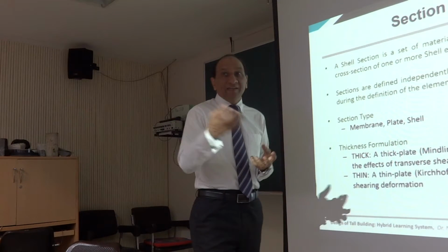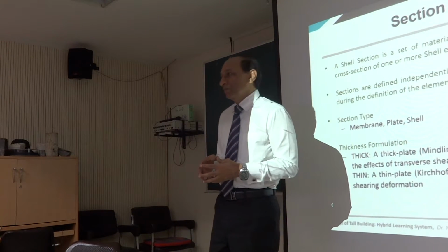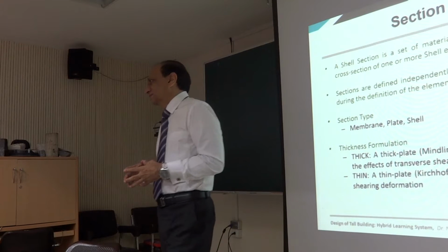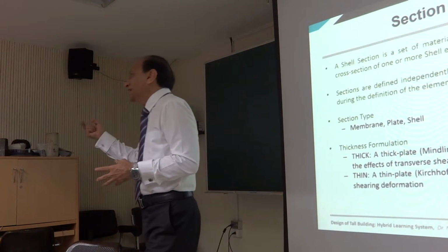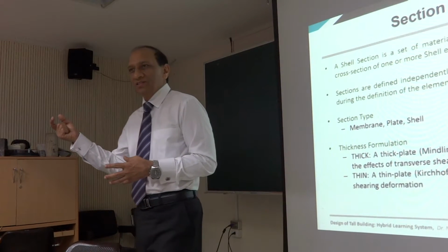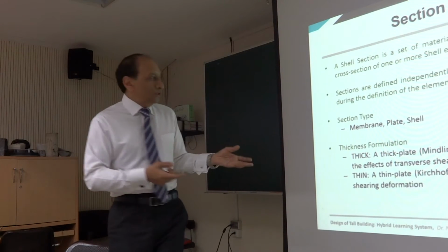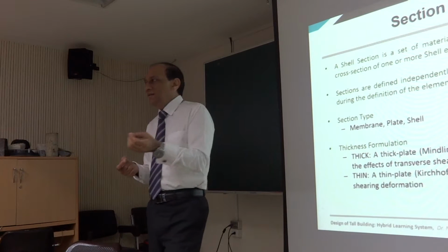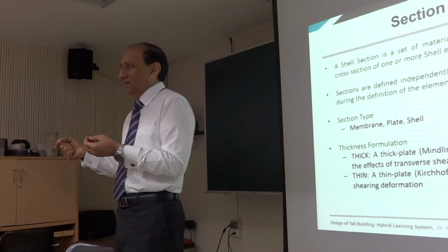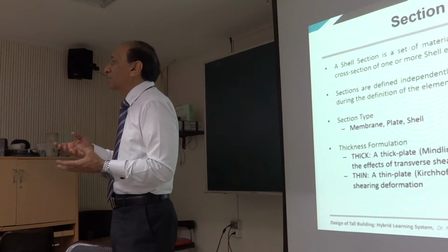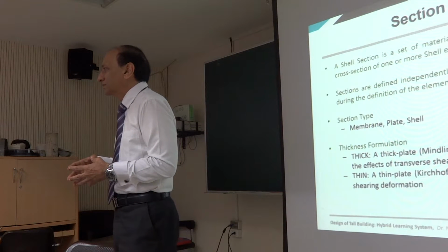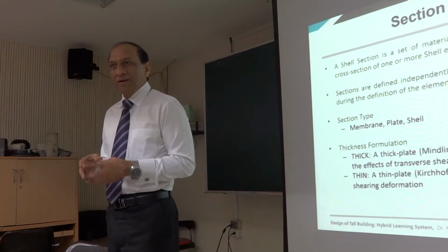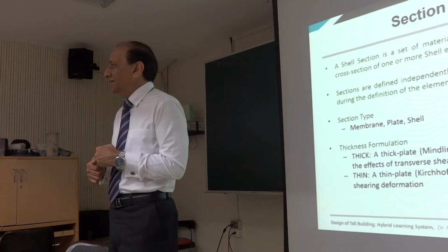For line element, we cannot do much material modeling, right? Only E is primarily what you can change. But in here, you can manipulate by using the Poisson's ratio and E, 2 more properties. So you get better modeling capability. But only thickness is enough. You don't need anything else.